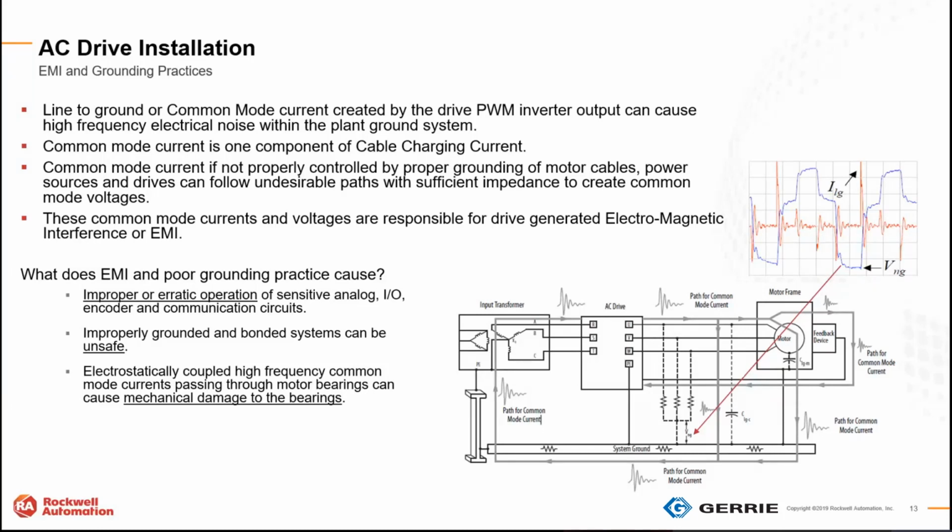If things aren't properly grounded, we get a lot of EMI, radiation or noise pickup. It can also be unsafe if we're not grounded properly, or we can do some mechanical damage to the bearings. Oftentimes if we have some induced high-frequency currents in the rotor of the motor, they tend to make themselves through the bearings of the motor. That's why when we have a VFD rated motor, the bearings are often insulated to help alleviate that, because we can get severe mechanical pitting of the bearings within the motor.